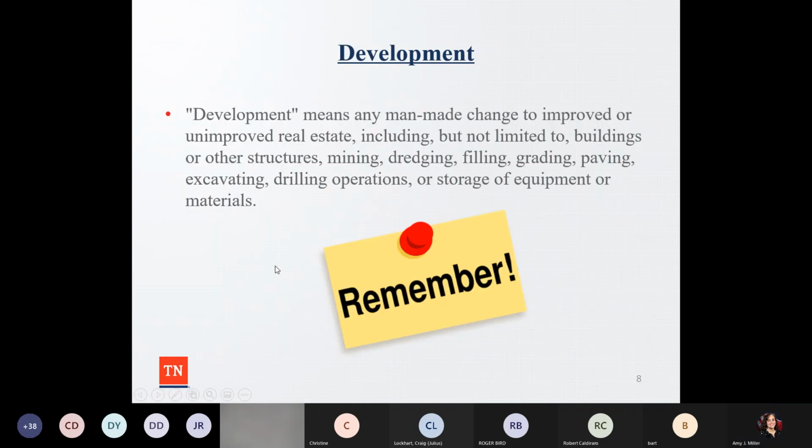So for the National Flood Insurance Program, one of the basic criteria of the program is to have the definition of development. Because if we're talking about floodplain and we have all these additional requirements for development that's in a special flood hazard area, whether it's in a zone AE, zone A, or floodway area, there's certain standards and criteria that have to be met.